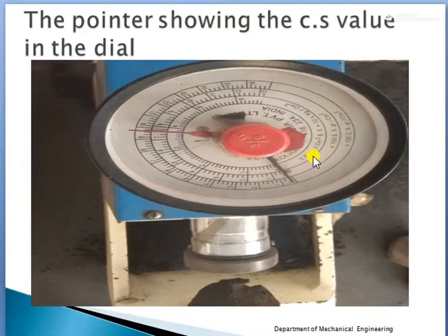For compressive and shear strength, you check the sand specimen in wet conditions, that is, with some moisture in it, while performing the experiment. For taking the reading of tensile strength, it should be dried. But for our study, or the syllabus, we have compressive strength and shear strength.